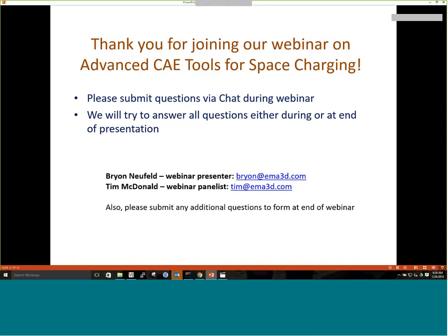And the next question, this is one for you, Brian. Can the mesh resolution be different for different regions of the model? Actually, it can be. You can, in Cadfix, change the mesh approach based on sets. So you can pick, for example, the solar cells, one particular tolerance, and you can change the tolerance and other features for other regions, and the boundary measure will make it all match up nicely.